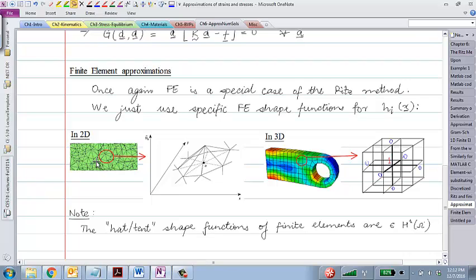In general, there are some other types of approximations also. But for simplicity, let's say that we'll break it up into triangles. If you look at a particular patch of triangles within this domain, that patch might look something like this. And if you remember, in 1D, when we broke this up into elements, that created nodes.